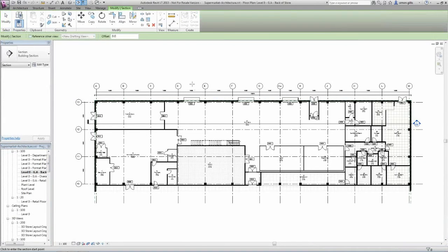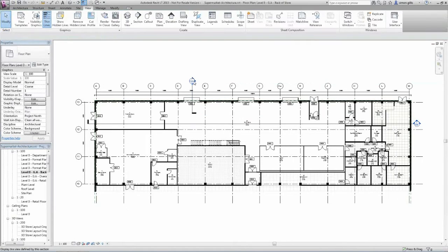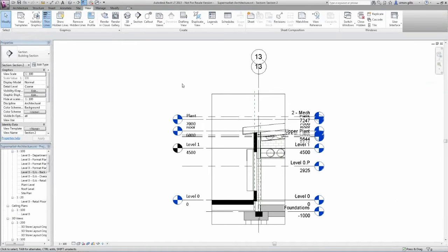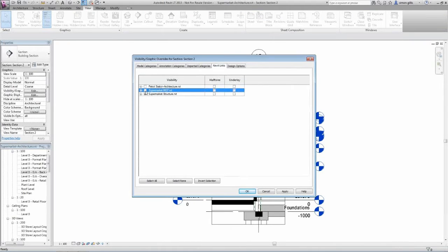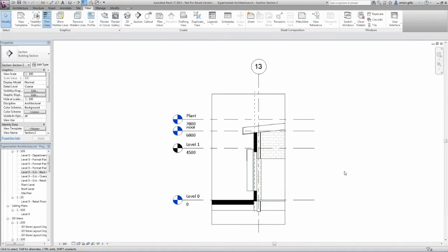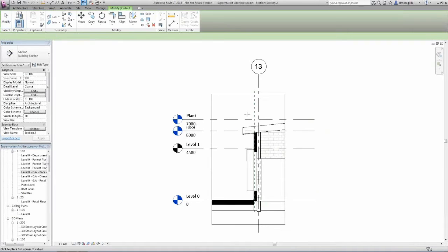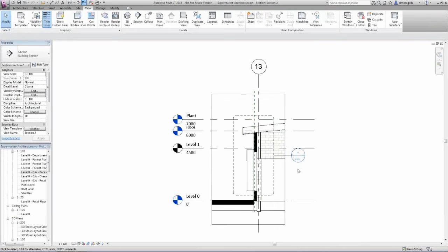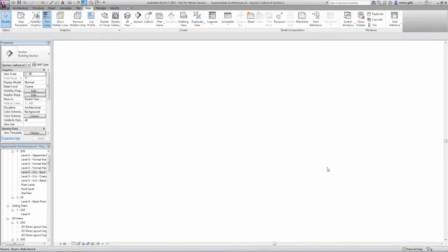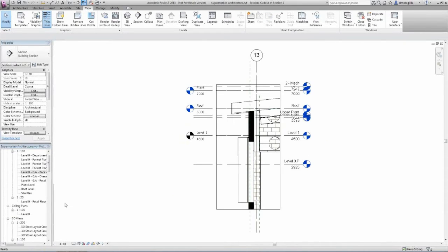Let's look at, whilst I'm on the theme of sections, I'm just going to draw a section through another part of the building here, through the dock shelter for the lorries to access. So I can go into, and create sections. From those sections, I can also create call-outs. Okay, so I can go in and zoom into areas of those sections. I can open that automatically. I can change the scale.